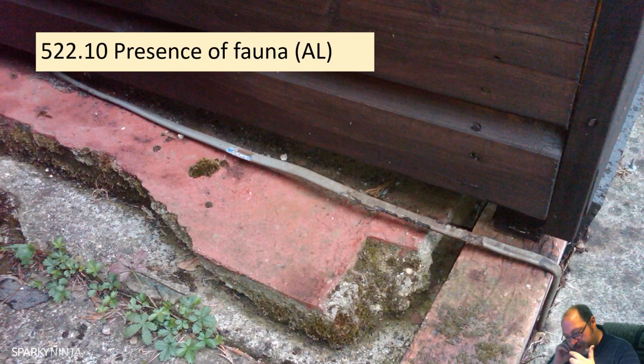Earthquakes aren't too common, but it might be seismic effects such as a bridge or road movement, or it could be the railway that you're adjacent to, and there could be some vibration. So you've got to consider, if there's a bit of flexibility in the building construction, or if there's a bit of vibration, you've got to assess for that risk with your wiring system choices. It might be that a rigid metal conduit system is going to put some stress on it.